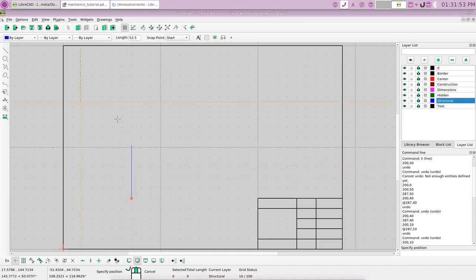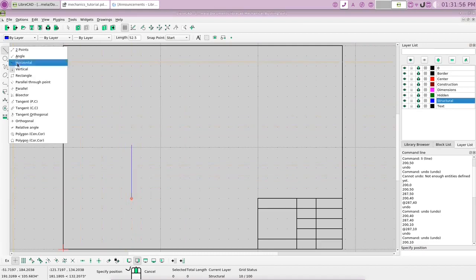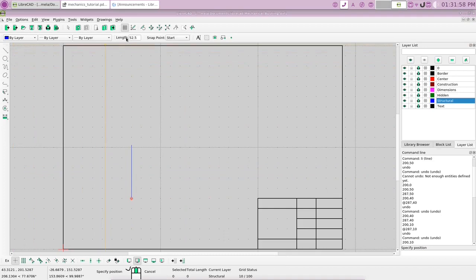So let's go ahead and get a horizontal line. It also has areas that you can configure. Okay, and let's turn the snap on to snap on end of line. Okay, but this line here is not 52. This line here over is 4.5, I believe, is it? 4.5? And let's snap on that, okay? There we go. Now the next line, again, is a vertical. So let's go back to vertical, and it is 7.5, I believe. Okay? So let's go up 7.5.